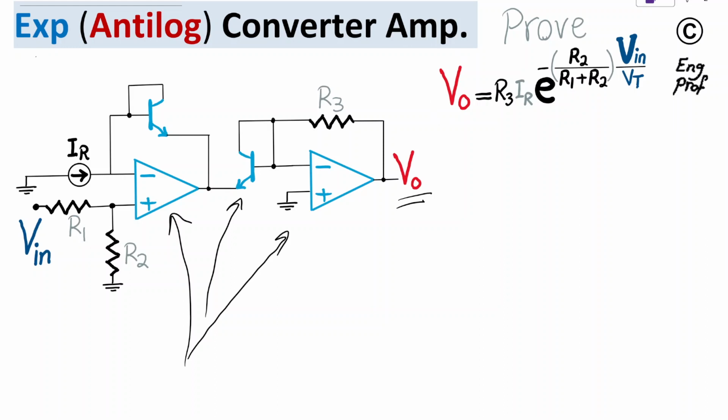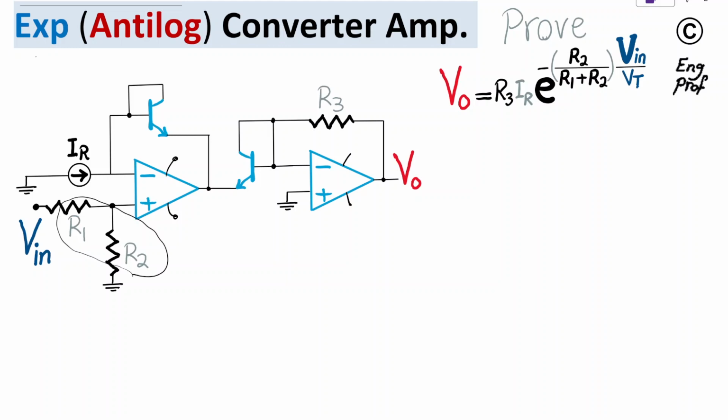How is this possible? It's an interesting circuit because it enables us to compute the EXP of, let's say, a given voltage at the input of the circuit. Okay, so let's make the assumption that op-amps are properly biased with the proper supply voltages so that they are operating in linear region for both op-amps. And at the same time, of course, we need to be careful about selection of the value of these two resistors,